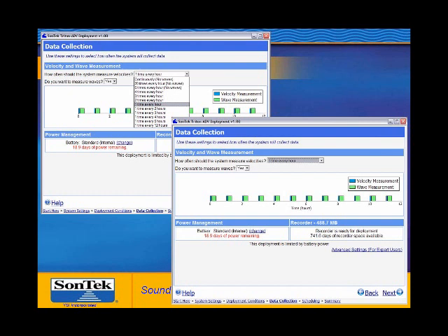Now typically, in the past people have had a lot of trouble working out exactly what are the best settings that they want to use when they actually collect wave data. So what we've done is we've simplified the whole process, and we've set the optimum parameters for collecting waves. Now, if you would like to set up the system to collect waves in your own way, those options are still available, and they're at the bottom of the screen under the advanced settings. So you still have that freedom and flexibility to select those sorts of options if you need them. But if you want to quickly get out there and deploy it and know that it's going to be working for collecting waves in a very standard and operational fashion, then it's very quick and easy to do.